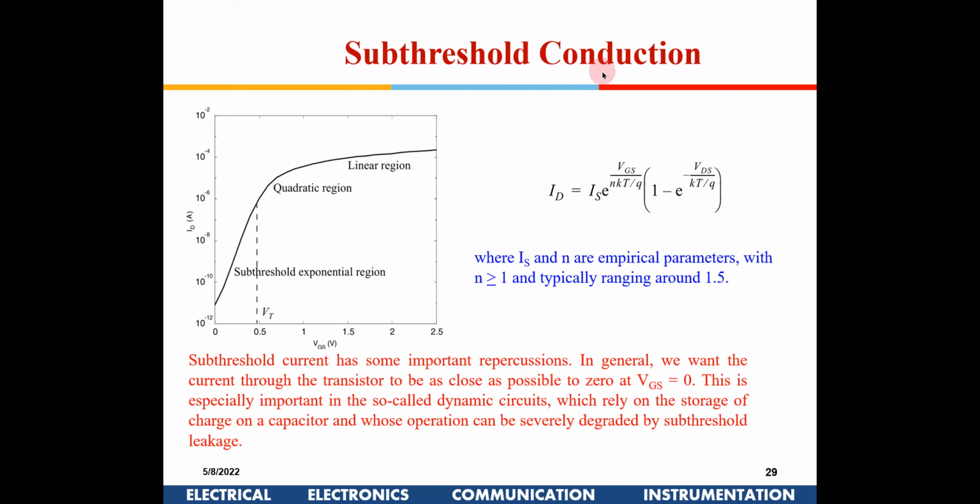The last concept we are going to discuss is subthreshold conduction. Generally for long channel devices, we assume that if the voltage is below VTH, the current is 0. But for short channel devices, the threshold voltage is very low now, because VDD is low: for 180 nanometer VDD is 1.8, whereas for 45 nanometer it is just 1 volt. Accordingly the threshold voltage is close to 0.7 for 180 nanometer, whereas for 45 nanometer it is around 0.45. So if VT is low, then even when the voltage is below VT, there will be a substantial amount of current. That is known as subthreshold leakage current.